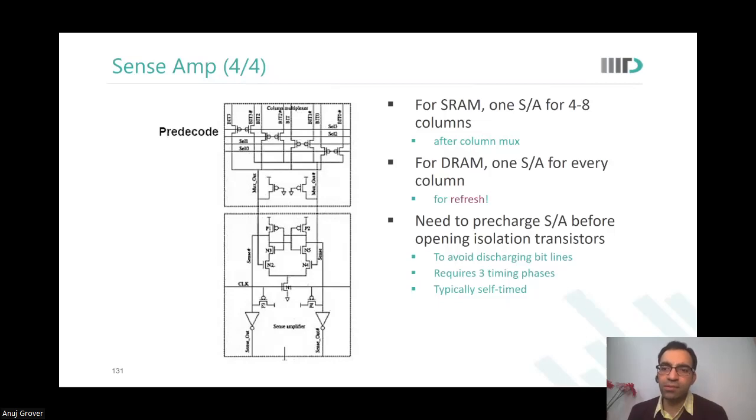Yes. I'm just giving you some random, gross, cartoon-type numbers. That is not the reality. Even in a DRAM, the array is much more area than the periphery, but I'm just exaggerating the situation for you. There are two different components for area. Periphery area is larger, okay, understood. But what about the array area? The array is so dense that overall DRAM is denser.